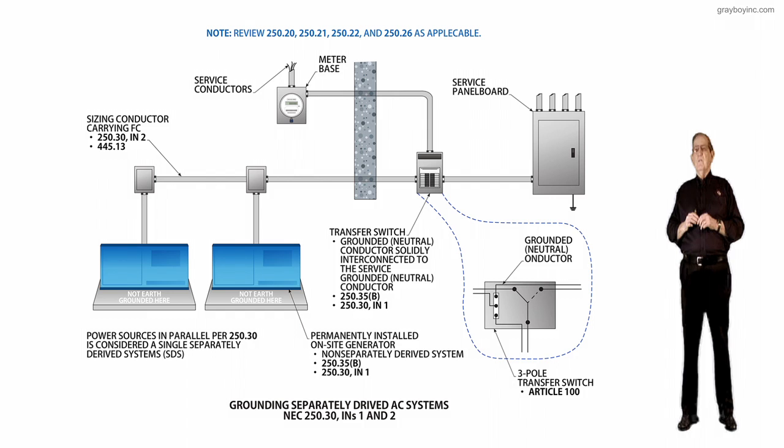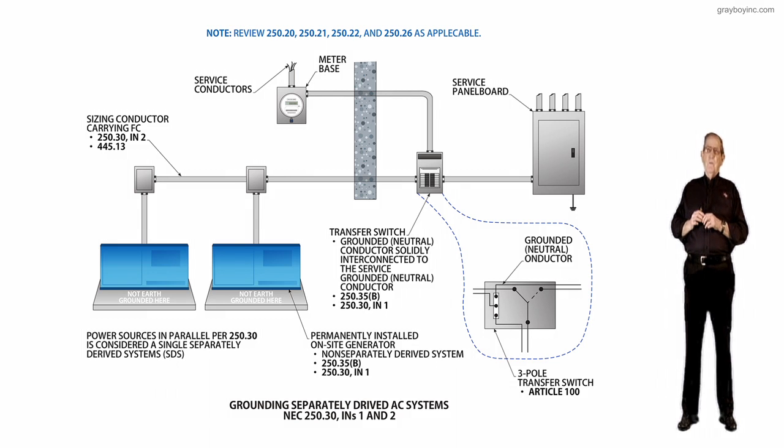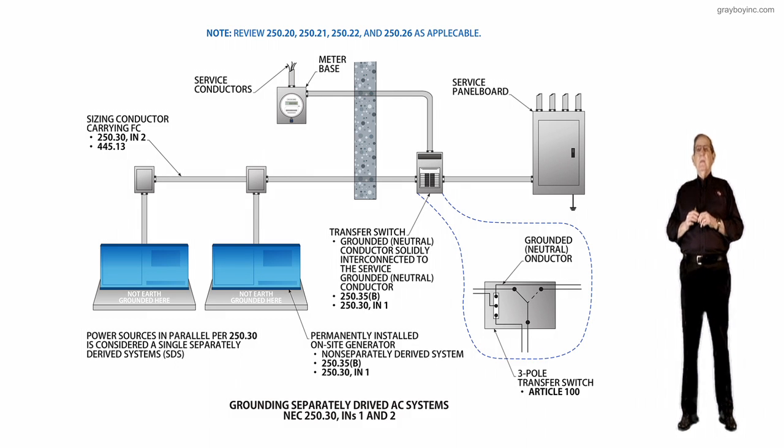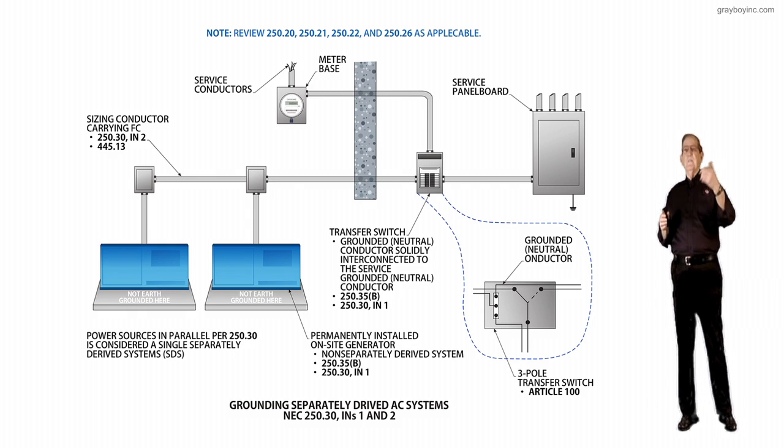And notice now you could have PV systems; you would pick that up over in 690. And then you would pick up 694 for wind generators. I believe it is 692 you'd pick up for fuel cell systems. Identify what your system is, but make sure the sections I quoted are fine by looking at the table of contents.